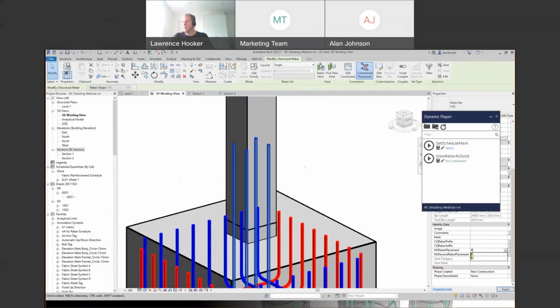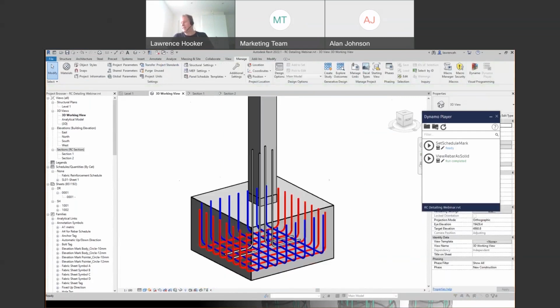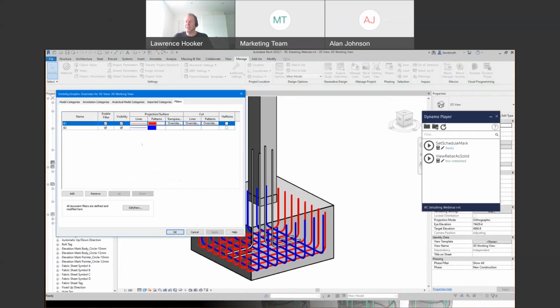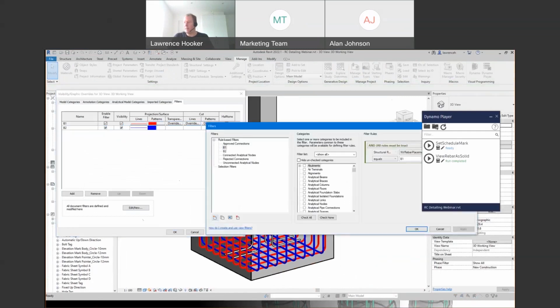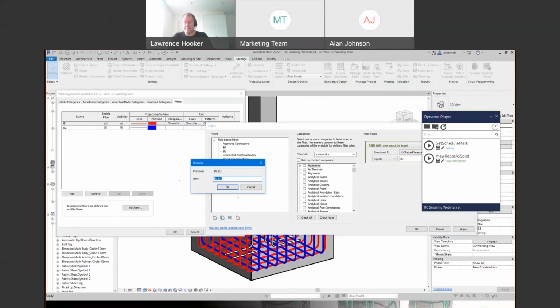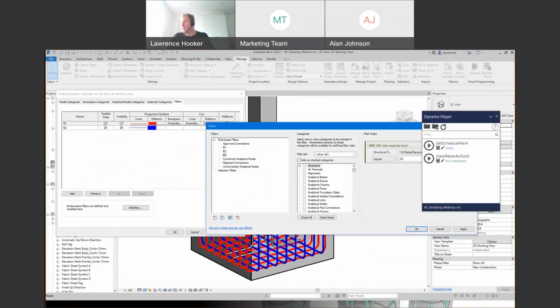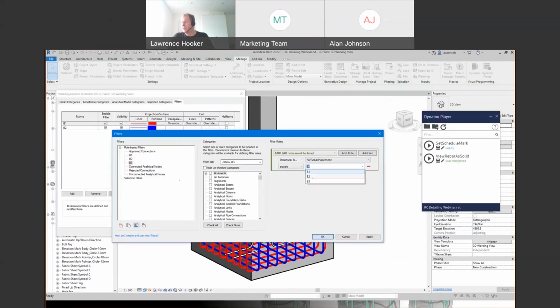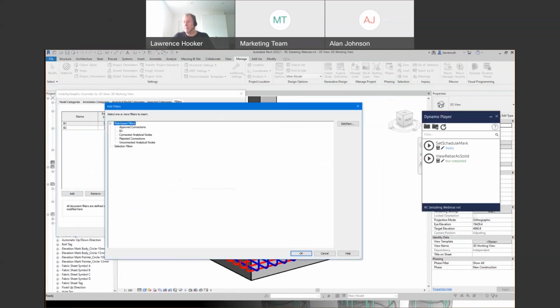And just to be a bit thorough with my filters, if I go back into the filter option here and we go to edit new, I can pick B2. This time I want to duplicate that. Let's rename that. And of course, that's now a B3 in here. And just like you saw me do before, I can just select B3 from that filter, add that filter in.